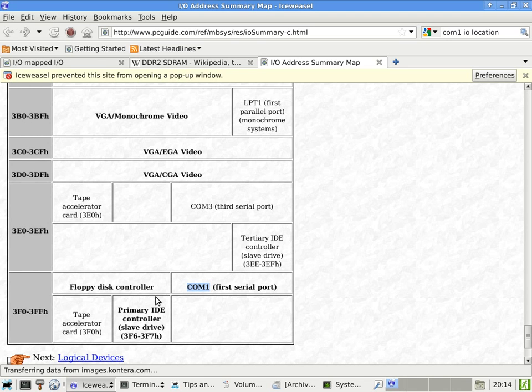Okay, we have another set of instructions specifically only to deal with the I/O space. Are we doing okay so far? We have two sets of instructions, one set to deal with memory space and one other set to deal with I/O space. That's what we call an I/O mapped scheme, okay, because we have two spaces.